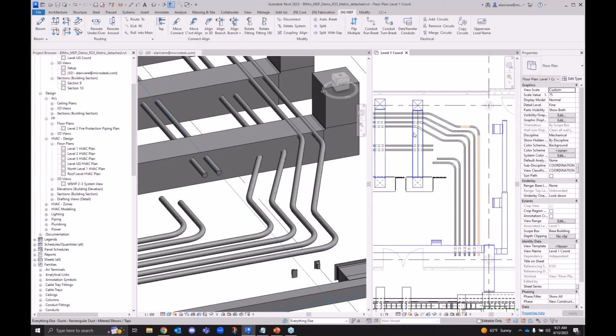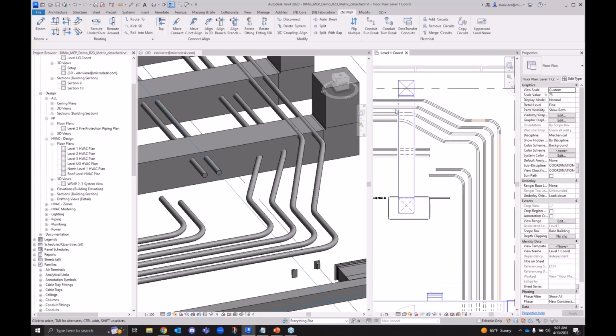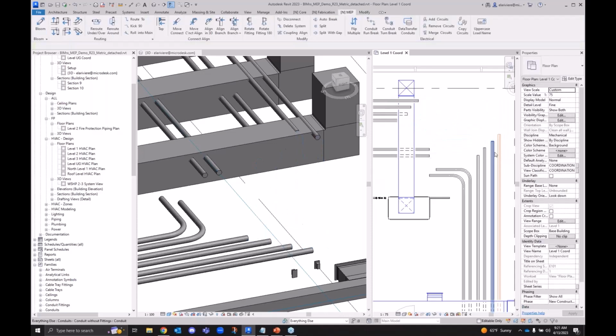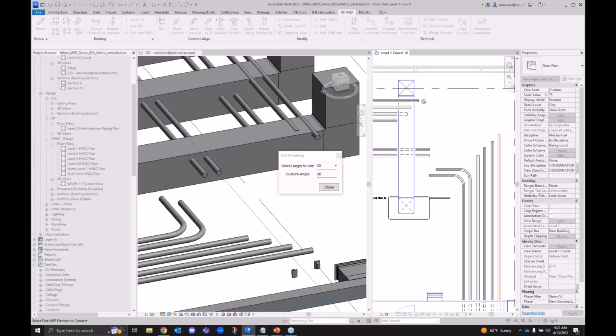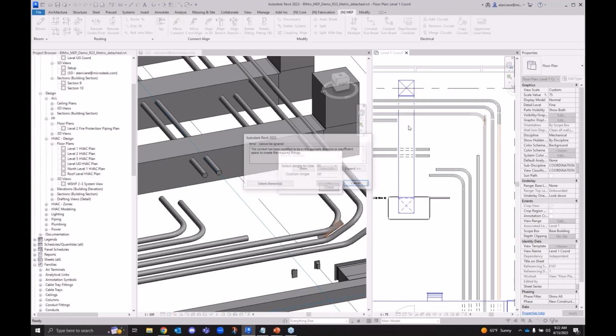And then another real quick note for you, because you may have noticed and said, hey, that looks pretty terrible. We would never do a connection like that. We would not waste that many bends. I'd agree with you. I would never waste that many bends. For anyone savvy enough to take a look below, we also have a kick 90 command, with kick 90 allowing us to do exactly that, a 90-degree bend to a 30-degree bend. So the first click being a 90, second click being a bend. 90 to a bend, 90 to a bend.